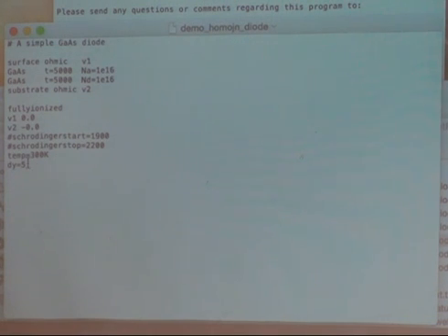dy is the mesh size of your length. If you are 5,000 angstroms, then your spacing is 5 angstroms here, so it's solving for every 5 angstrom. What you'll do is go in at every point, say here's the band gap, and then 5 angstrom later, here's the band gap, here's the doping, and it will first solve the electrostatic problem, the Poisson equation. And if you had asked it to solve Schrodinger, it will solve it too.